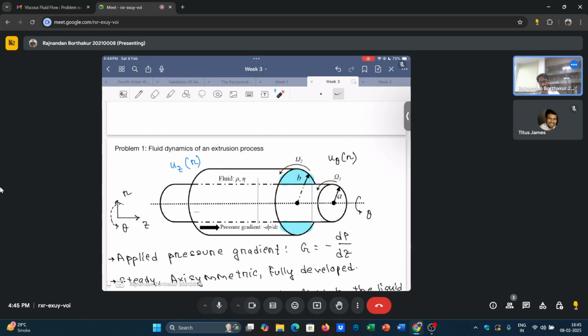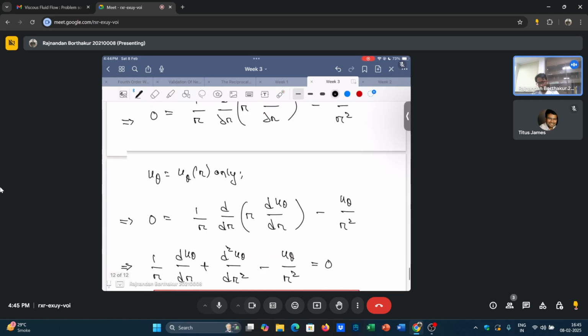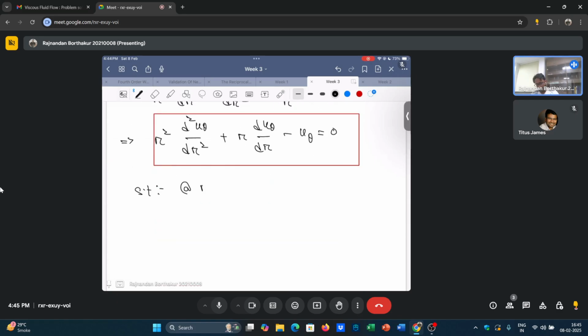Okay. So I know that at r equal to a and at r equal to b, the rotational velocity of the fluid is exactly equal to the rotational velocity of the cylinder, which means that I can write that at r equal to a, my u theta is... So here is the thing. When I write the velocity, I should write u bar at r equal to a is actually omega, which is the rotation of the cylinder, cross the radius. Omega 1 is the rotation of cylinder 1 cross the radius a, and this is basically a times er hat, which is the radial direction.